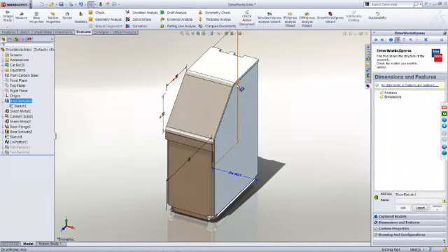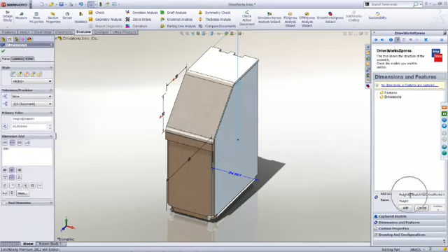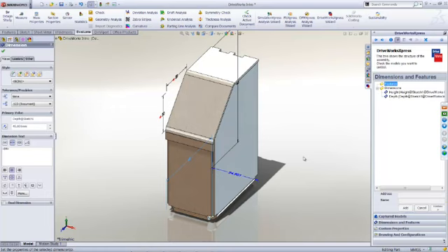Now watch what happens when I select the 65. Remember, it's height at sketch 1. By selecting this, not only does the system recognize that address, it also automatically adds the name height. Let's add this, and let's do the same for depth. Same thing here. Now, what I did not do earlier was rename this. It's still called D1 at boss extrude. So when I select this, the system has no idea what name it should be giving, so it's prompting me to give the information. I'll say width. Really imaginative name here.